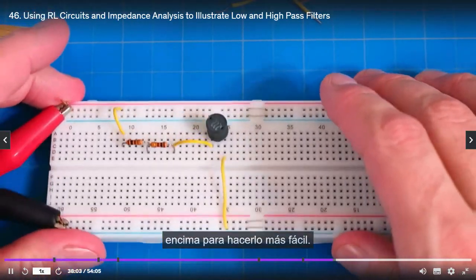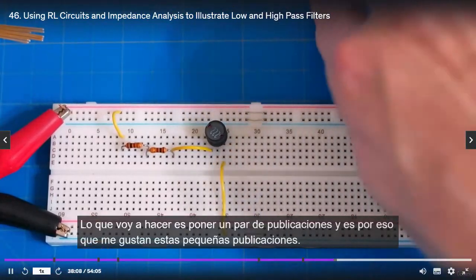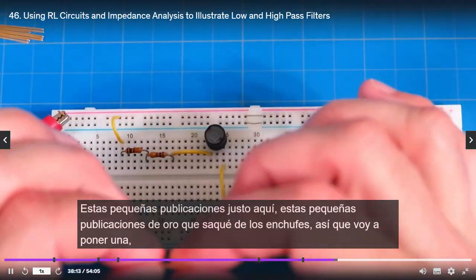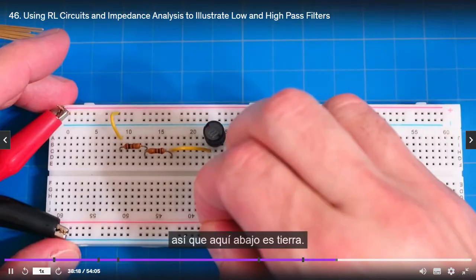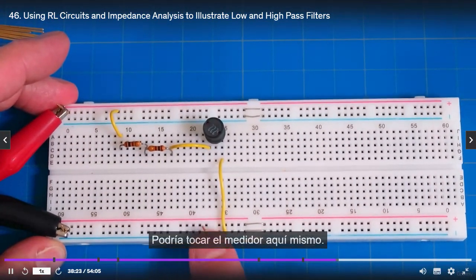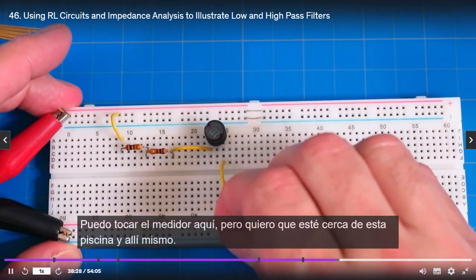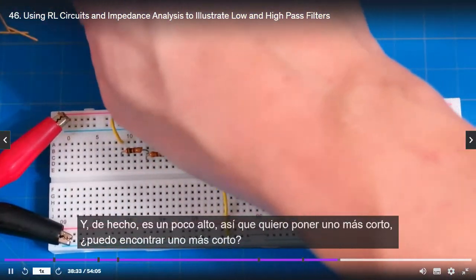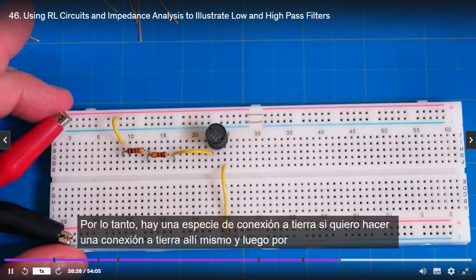And if we want to measure voltages, we're just going to take our meter and put it right on top of it. To make that easier, what I'm going to do is put a couple posts, and that's why I like these little gold posts, which I pull out of sockets. Down here, this is ground, so I'm going to put one down here at the ground. I could touch the meter right here, yeah, I guess I can do that, but I kind of want it to be close to this. So I'm going to put one right there. In fact, that's kind of tall, so I want to put a shorter one. Can I find a shorter one? I think so. So there's kind of a ground right there.